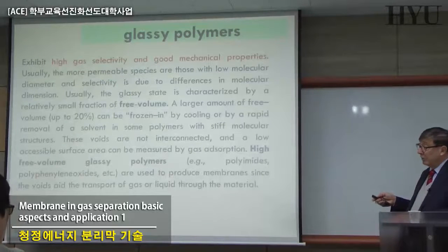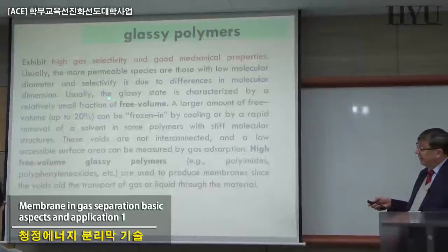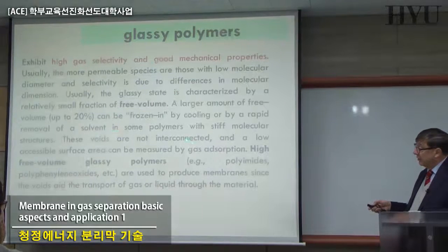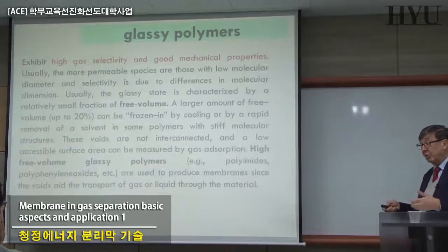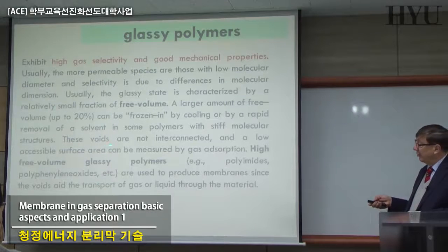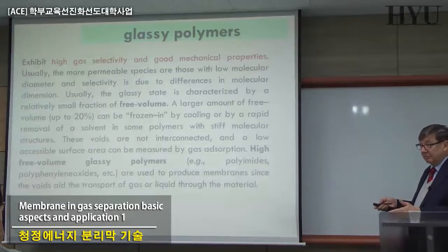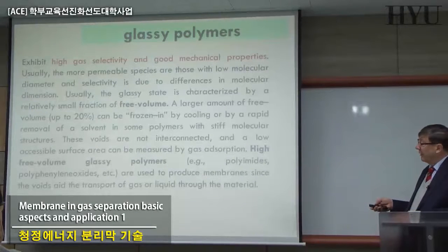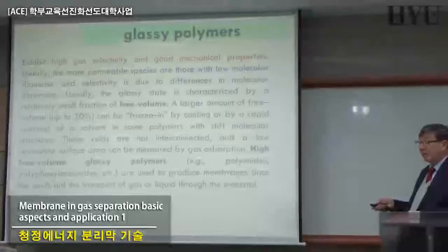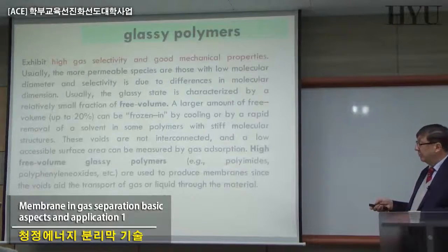However, remember that the free volume that you can form in your glassy polymer very often is not interconnected. So it's not 100% available for the transfer of the penetrant. Some penetrant can be blocked in, and that is one of the problems that eventually has to be solved. And also, the surface available on the membrane for the penetration of the penetrants into the membrane matrix can be relatively small.